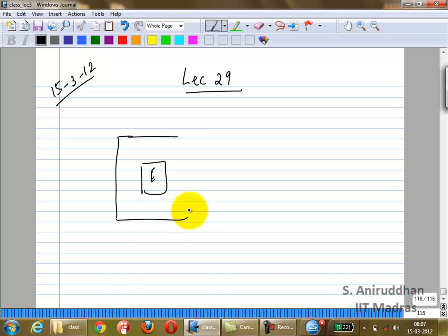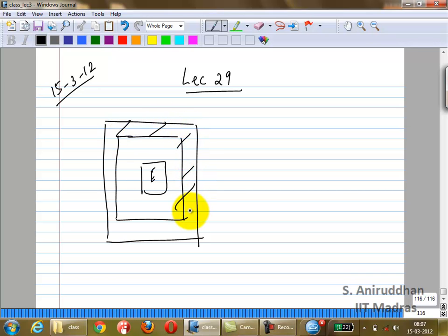So let us say I make this my collector, which means lateral current flowing in all directions is captured by the collector. This is the top view of the device. So current is still flowing horizontally. In this case it's a PNP, right? So the current is flowing from your emitter to collector, and you capture currents going in all directions. The only current you don't capture is the vertical current. Correct? So you vastly improve your beta. Is that clear?